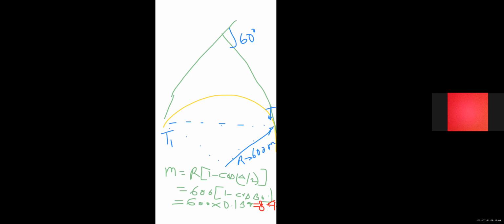The question is: the chainage of intersection point of two straights is 1585.6 meter and the angle of intersection is 140 degree. The radius of the circular curve is 600 meter. So what are the tangent distance and length of curve?